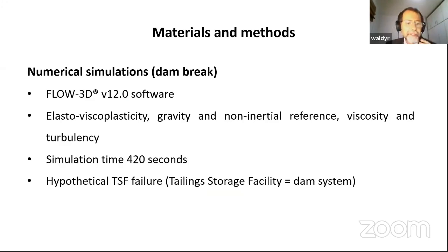The numerical simulations were done using Flow 3D software, its latest version. We tried other software as well, but this one was the one that was nice for us as far as our understanding of the mud flow. You're going to see that you don't need to input a hydrograph of your reservoir in order to have the dam break study.